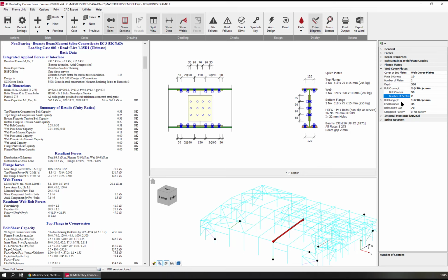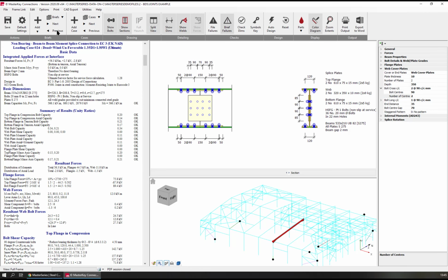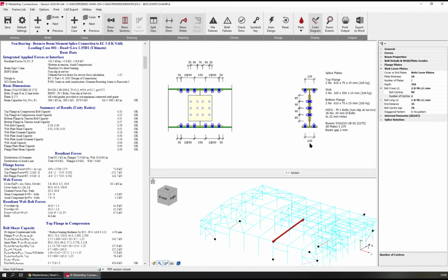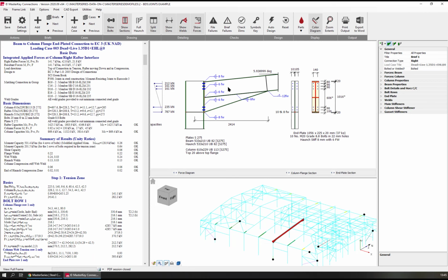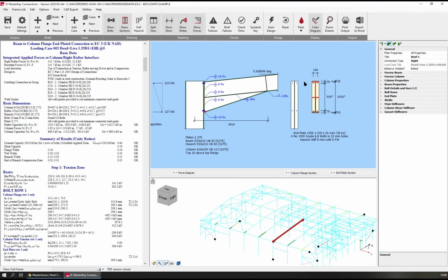All sorted and done. And we'll just scan that for all of the loading cases, and it's just going to check all loading cases, and there's no problems there. Now, another beautiful tool that we have, and this comes into play very much in the likes of the eaves, is the ability for the software to do the design for you. So what I can ask it to do is to come along and empty out most of the trash. So it's just got the basics, 1 row of bolts, and in this case a compression stiffener. I'm going to take that one out, put that to 0.